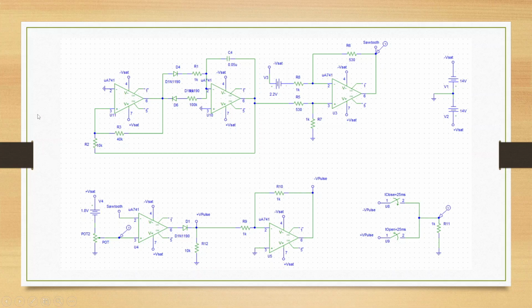Basically, the circuit starts from the left of the page with creating a square pulse which is passed through an integrator circuit to produce a linearly changing voltage. The resulting waveform rises gradually and falls sharply, which is the characteristic of a sawtooth wave.